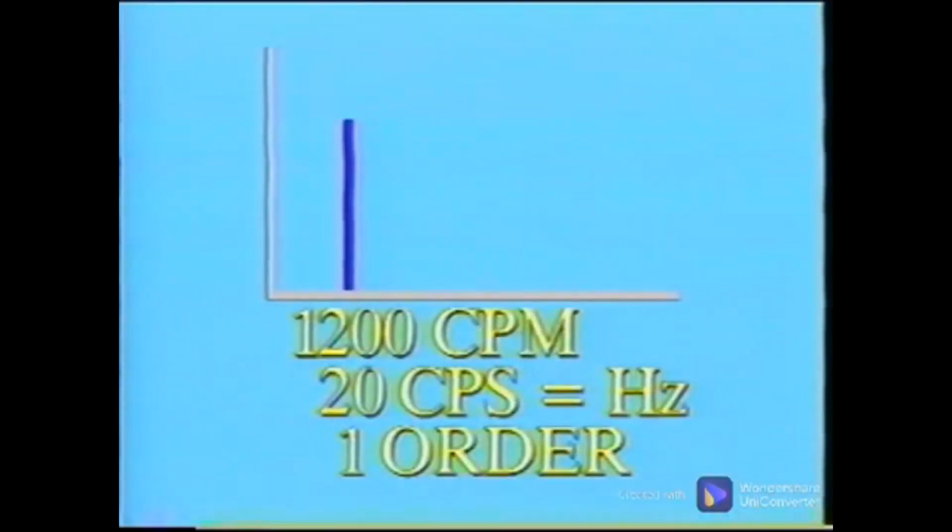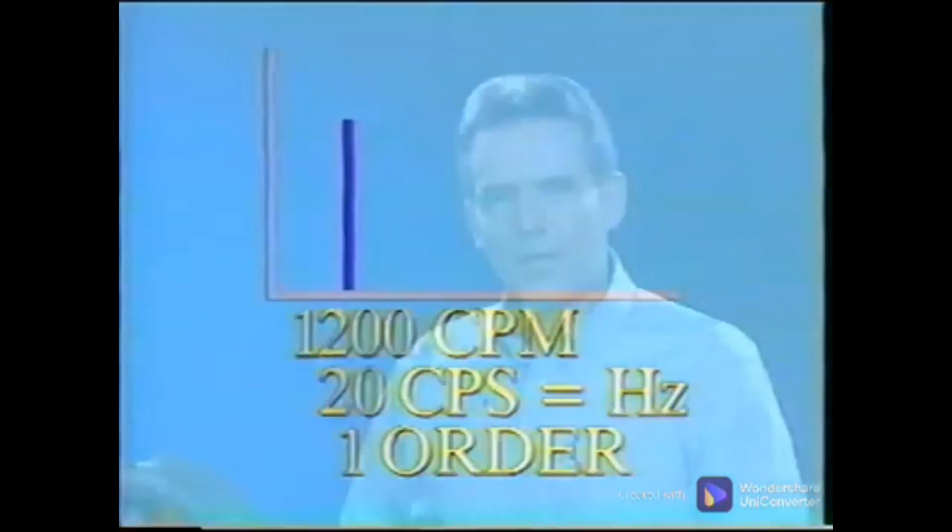The frequency units are displayed in CPM, which is the number of occurrences per minute, Hertz, which is the number of occurrences per second, and orders, which is directly related to the turning speed of the shaft at the measurement point. There are times when one of these units may be more helpful than the others in looking for a particular fault. Other times another unit may be more helpful. Use them to maximize your analysis capabilities.